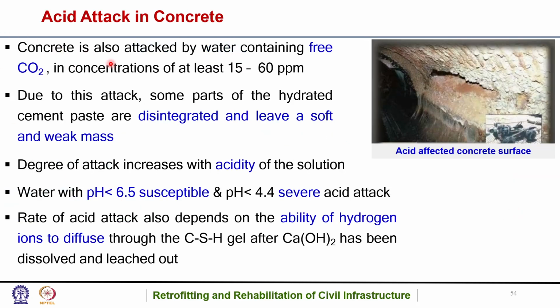The concrete is also attacked by water containing free carbon dioxide. That is similar to carbonation corrosion. It is attacked by water containing free carbon dioxide in concentrations of at least 15 to 60 ppm. Due to this attack, some parts of the hydrated cement paste are disintegrated and leave a soft and weak mass. The degree of attack increases with acidity of the solution.